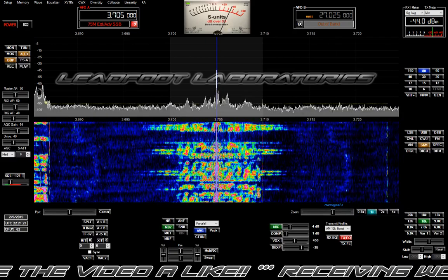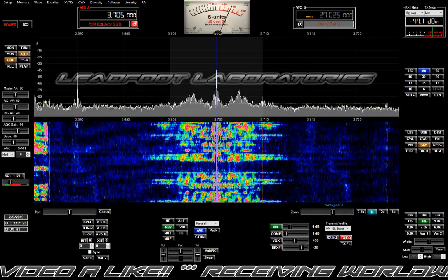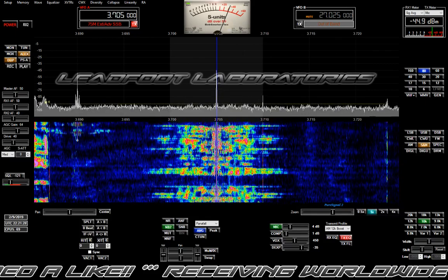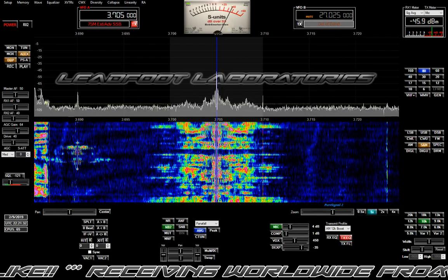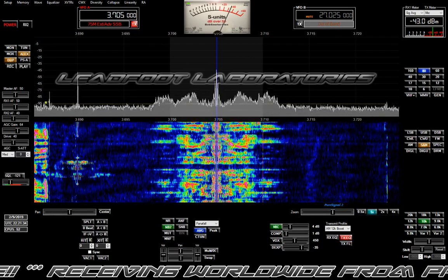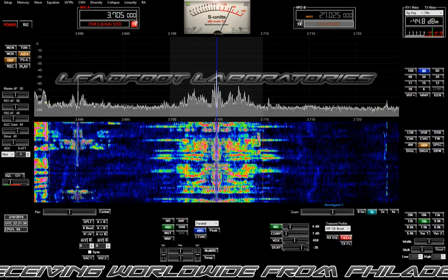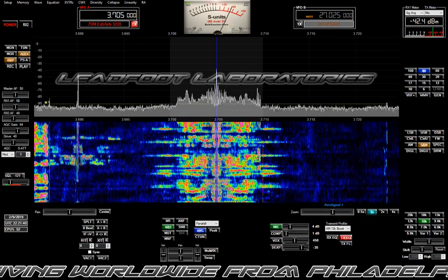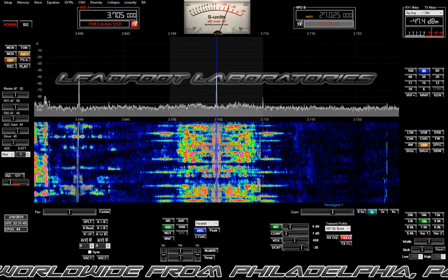You know, it's interesting, too, about the whole concept of intermodulation distortion with linear amplifiers. I don't know, Frank, if your linear has what's called pre-distortion. I'm sure you're familiar with that concept. It's not that new, but it used to be done in the analog domain. Now I think it's done with digital sampling and correction.